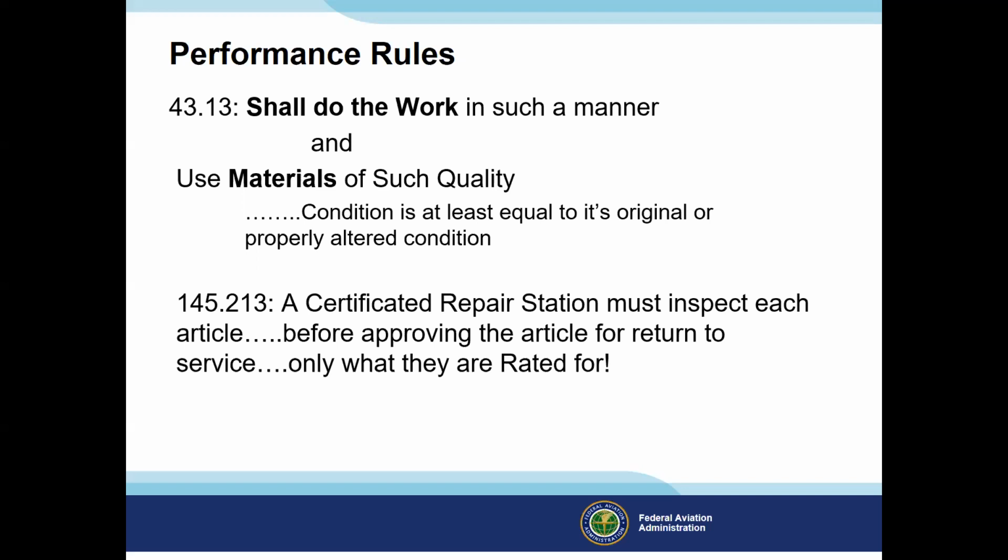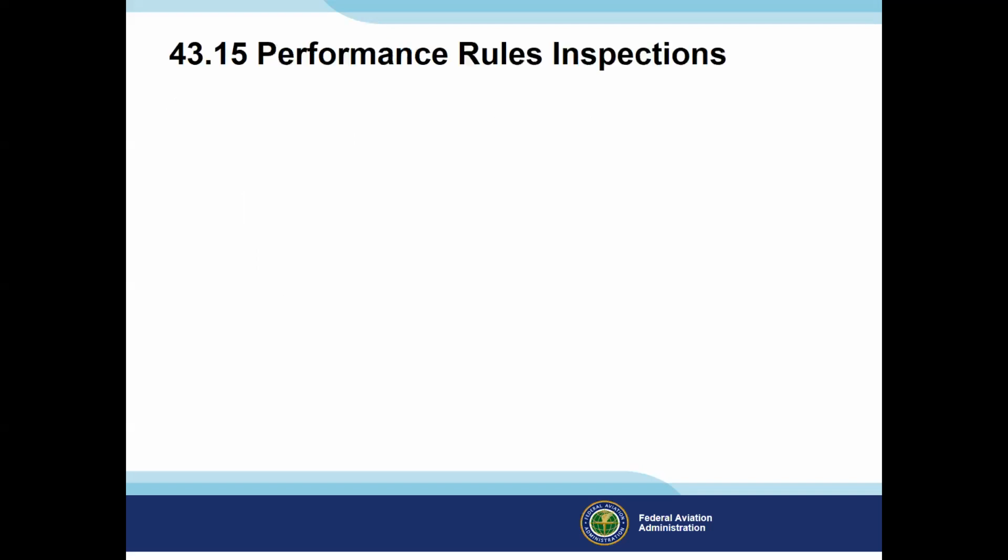As a repair station, they must inspect the article before return to service, and they will follow their quality system. It's important to note the repair station can only work on items they're rated for. And understand that for those parts that you get, you are responsible for the parts that you install. Next slide.